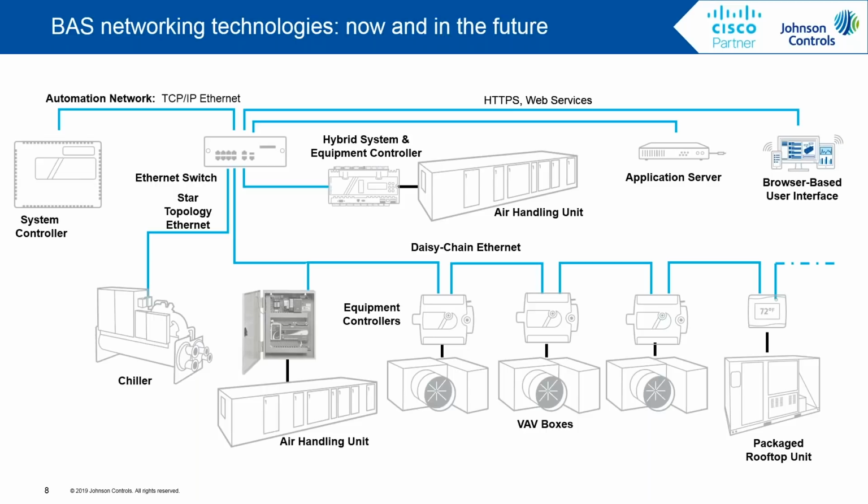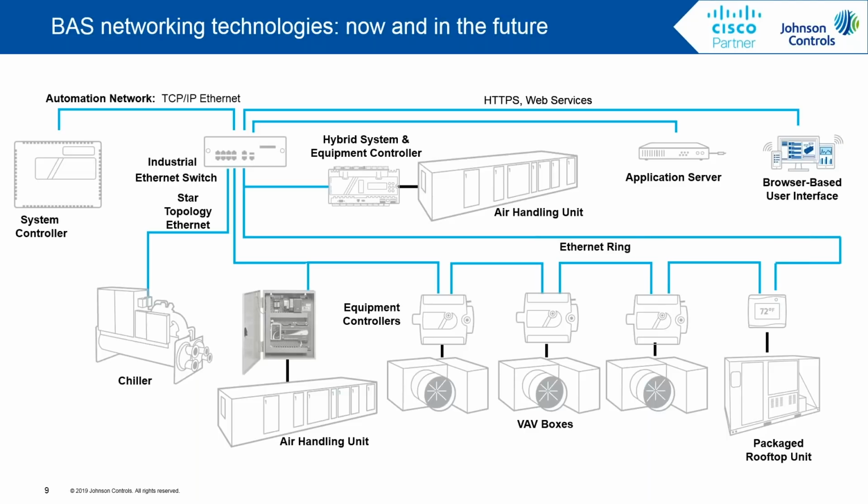Now, there are some challenges and opportunities with using IP Ethernet down to this layer, and it has some issues of its own. From a topology perspective, Ethernet has different rules than serial or RS-485 based networks. Nodes on an Ethernet network can be connected in a star topology, where the Ethernet cable is run from the switch port to the controller node.